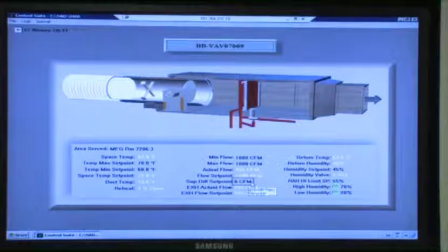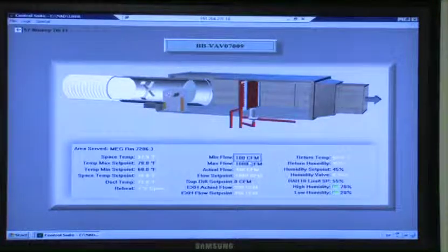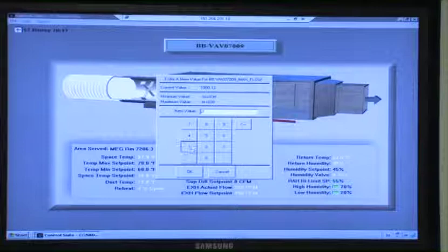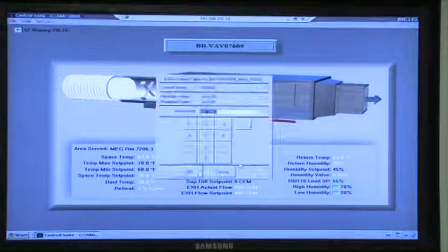Differential set point 0, I'm assuming because the exhaust is going to match that. It's a constant volume neutral room. You can change those to what they're supposed to be, Steve, if you want. I'm just checking. I believe they were 100, but we're just doing some of the flow switch to get more flow for it. But they are 200 and 100. Max flow 200, min flow 100.